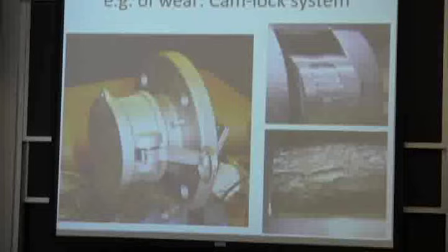Now think of it, they're not always going to put the cap in the same orientation. So if you move the cap around a little bit, you'll wear all around the flange, the piece that's underneath here. But these cams get worn out each time. So what you want to do is put the higher hardness on the piece that's the smallest, that's always going to be worn out. And they just didn't do that. It's not that hard to do. It's a small piece, right?